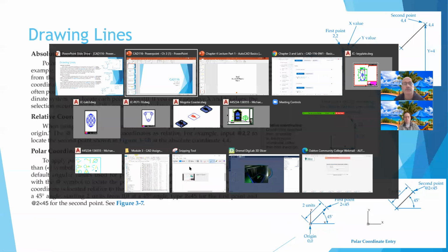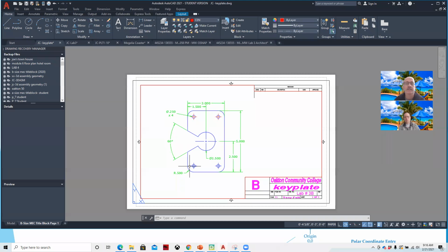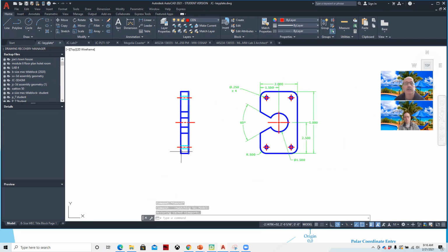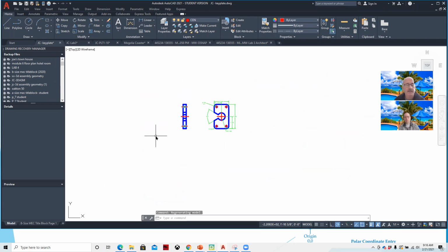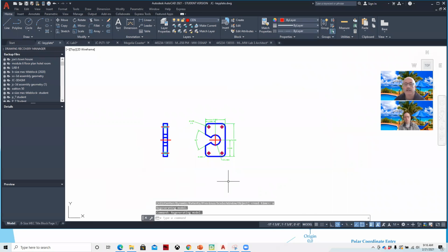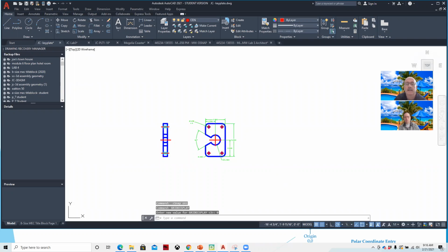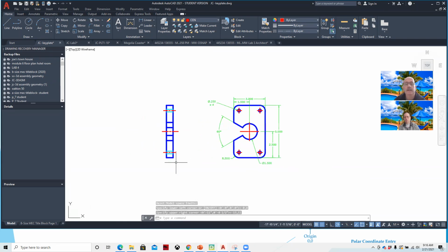And so as we start to work with these different drawings, for example, on a mechanical drawing, if we come back here to the model space and we look at this drawing, and if I say Z for zoom, A for all, and if I turn on my grid display, and I'm going to dial my grid display down to 0 so I can see the limits. And it doesn't seem to be set up properly. We'll come back to that.